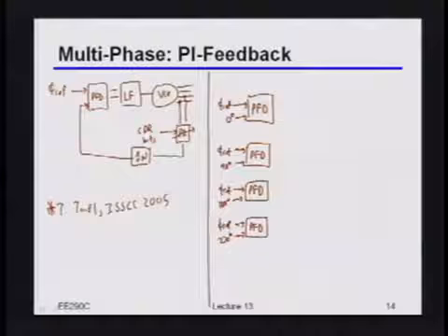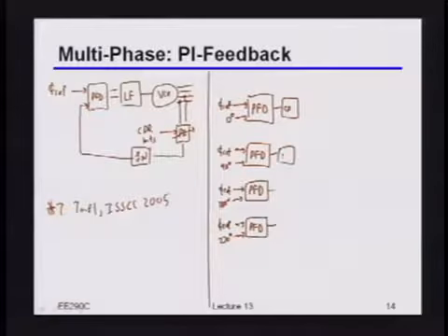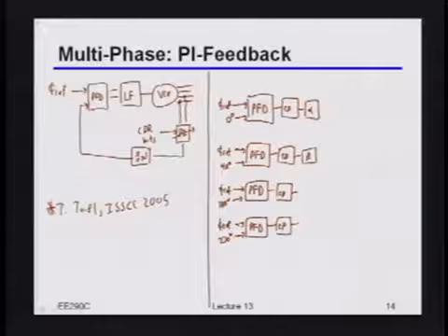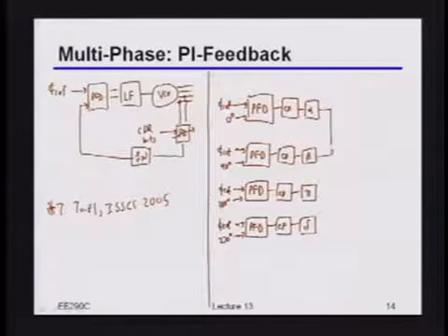Okay? Well, so now if I do that, you should think of the output of the PFD as maybe including, well, okay, let's be totally clear, we'll add in the charge pump directly afterwards as well. And now really, if I just take those charge pump outputs, and I scale them by different weights for each one of those phase frequency detectors, and then all I do is add all those things together in the current domain.